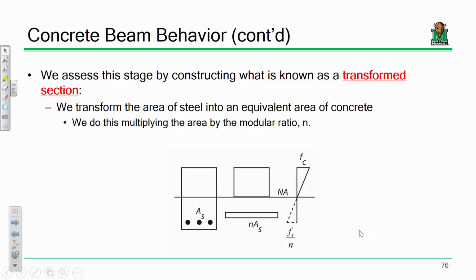So we now have to start considering the steel. Sigma equals My over I assumes that you have a beam made of one material, and that's obviously not the case here because we have a concrete beam with steel reinforcement. So we have to transform that steel into an equivalent lump of concrete. I don't really like this image on the slide because this lump should be in line there. It should be a little bit lower, so that it's all on the same line, because that's the whole point. The steel has to be in the same area. Then we'll use that to transform and determine stresses accordingly.